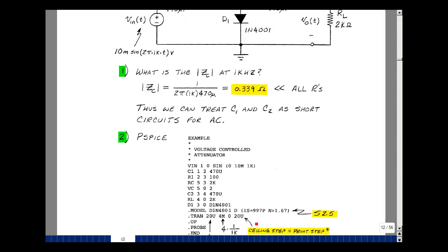And then we're going to use the model that we developed in Supplemental Problem 2.5. Semiconductor begins with dot model. Here we have a name, and I'll make the name the part number. What is it? It's a diode. We'll later change this for transistors. It has a value of I sub s and eta, as we talked about in the lecture notes.